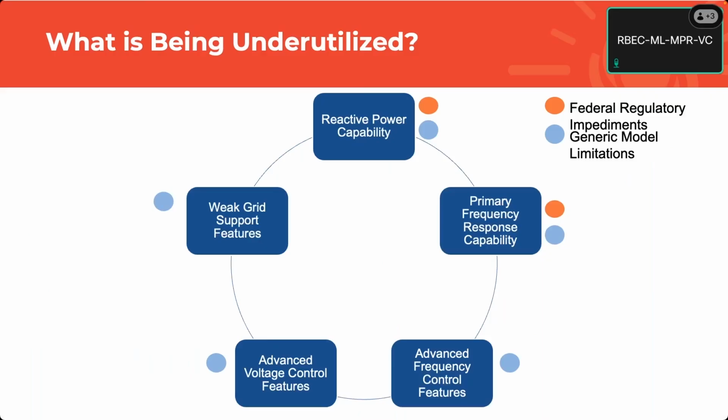If anyone wants to file with FERC, they're asking for it. I think MISO may have done that. But basically what the FERC order says is to be within negative 0.95 and positive 0.95 power factor, which means you limit your power factor. So that's a big misconception, or a big miss there.